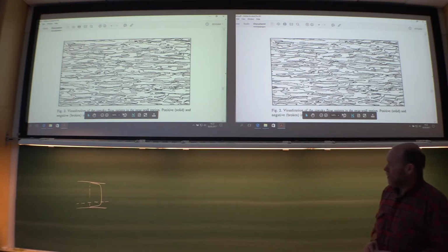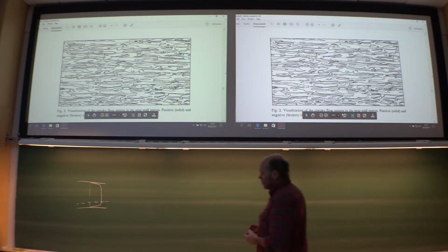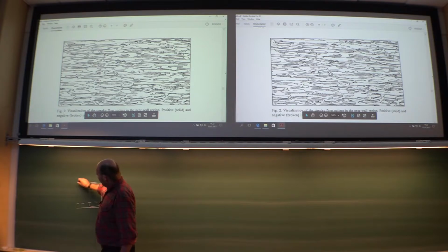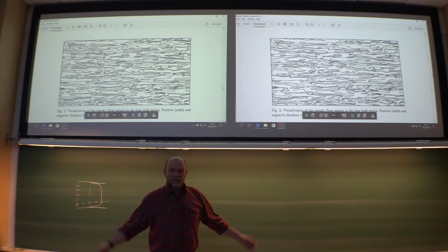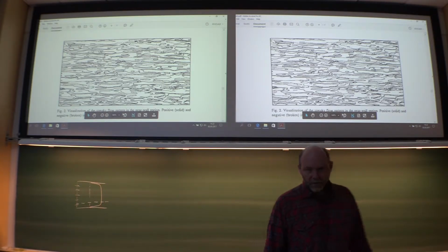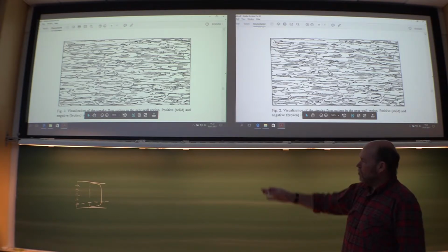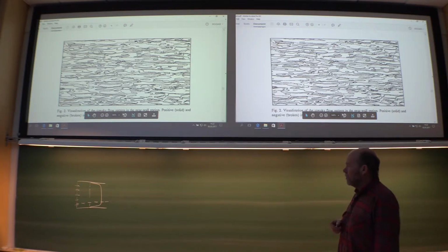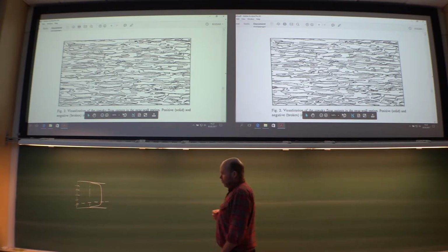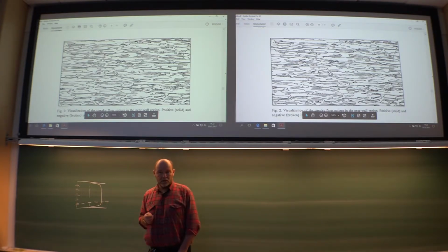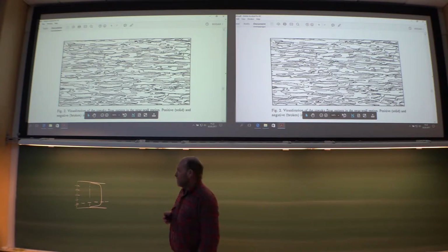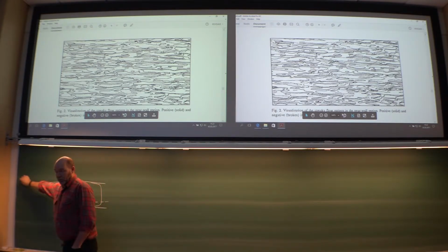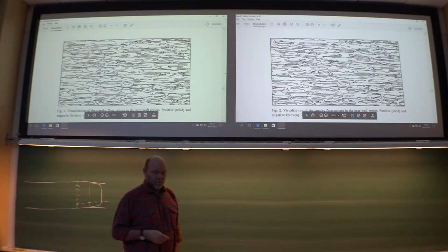Cyclic boundary conditions. Because, I mean, you have no option. How else should you find a complete, fully developed, correct, correlated inlet velocity that is turbulent? You can't get it. So you have to use these cyclic boundary conditions in order to achieve a simulation at all. Or else you need a very, very long channel. Extremely long. So just forget it.